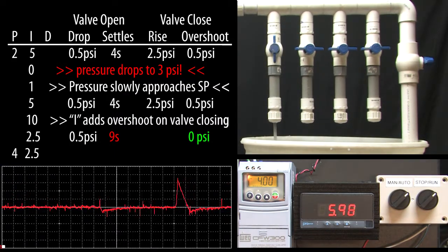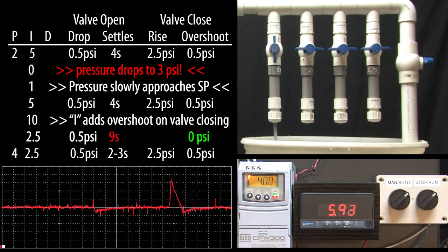And sure enough, we're now settling in 2 to 3 seconds and have minimal overshoot on the valve closing with no oscillating on the response. That's a pretty solid compromise. Now keep in mind this is how my system reacted. Yours will be different. But hopefully, now that you see what the coefficients do and how they work together, you'll be more comfortable with trying to optimize your system.